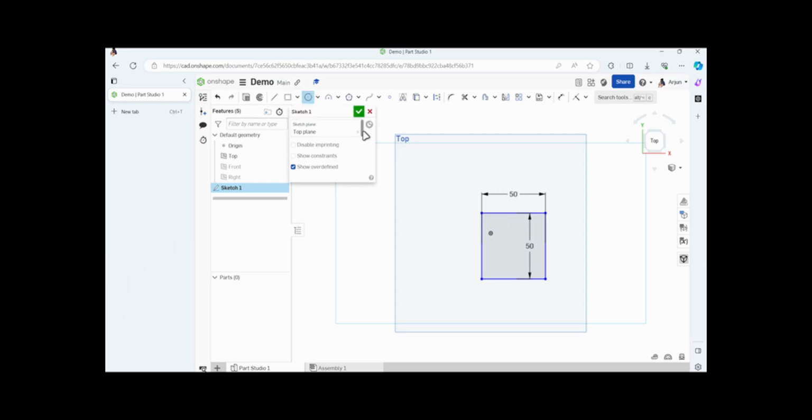So you can make a square, you can make a circle, and you can tell what the radius should be. Let's go 50 millimeters again, and it's as wide as our square is. Let's say I want to do a hexagon or a pentagon. With that, I'd click on inscribe polygon, and click and draw out how big I want it. The further I drag, the more sides they add, and the further left I go, it gets lesser and lesser. Let's say that a pentagon should be good. So let's do that.